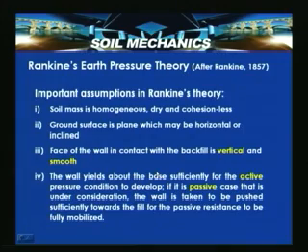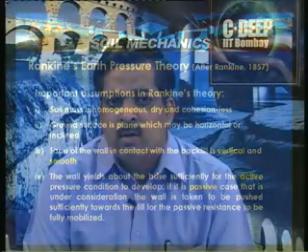That is, the back of the wall, the wall which is in contact with the soil, the interface is assumed to be smooth, that is a frictionless condition, which indicates that the wall has zero shear stress along the interface. So this particular condition, with the horizontal backfill and with a frictionless interface at the soil and wall interface, is also referred to as a Rankine wall.